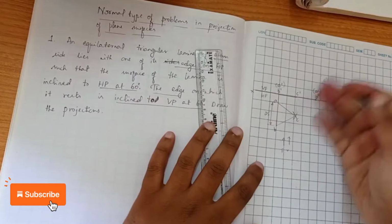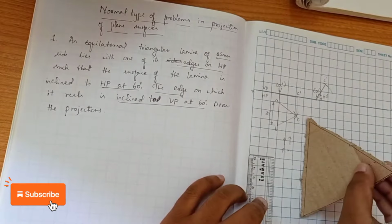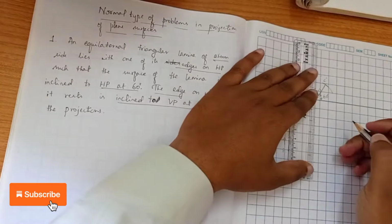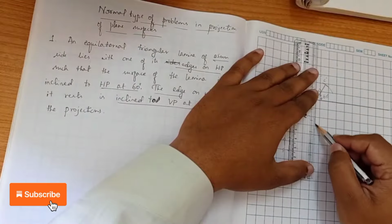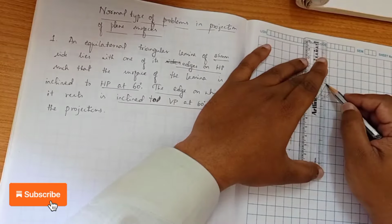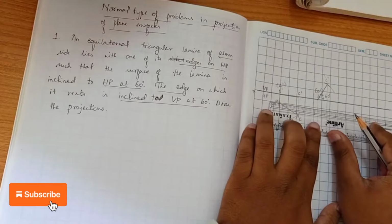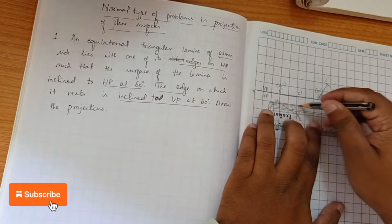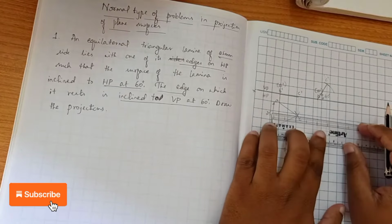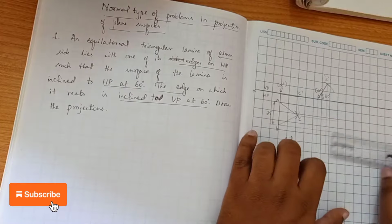Now we have to draw the inclined top view. Say this is inclined at 60 degree like this, so we have to draw the top view of it. How do we do that? Using the projection principle. You just follow the procedure, you will understand. So projecting the lines downward, from both front view and top view on either side, we can construct the second position inclined top view. So we have projected the lines.